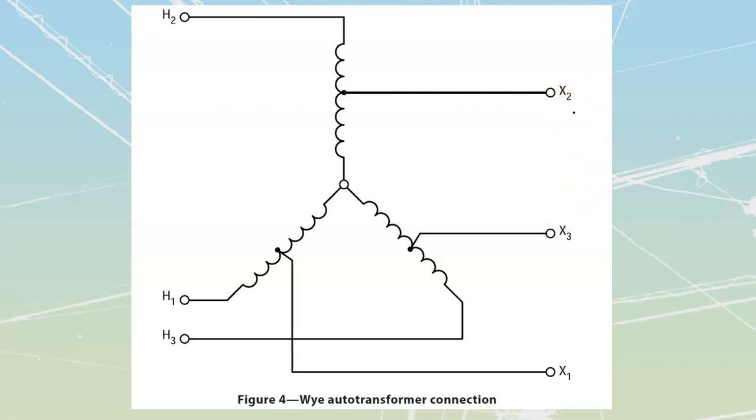The other way that it's going to be used is inside of high voltage transmission lines, where the line's coming in on these and then it's going to be coming out on these X's over here, and we can move up a tap or we can move down a tap depending upon what the actual line value is like. So we can use it to compensate for any loading on the line or any disturbances that we have. What it is not very useful for is supplying single phase loads.